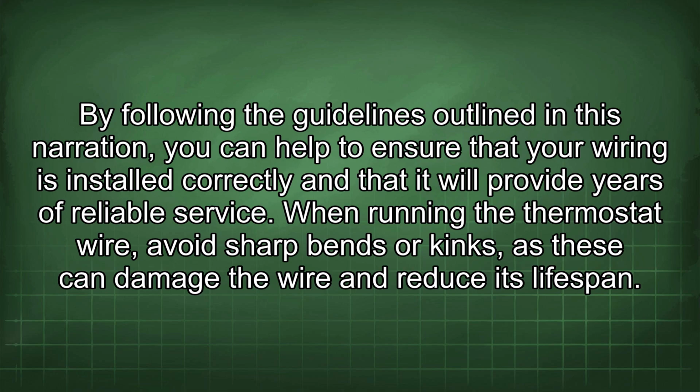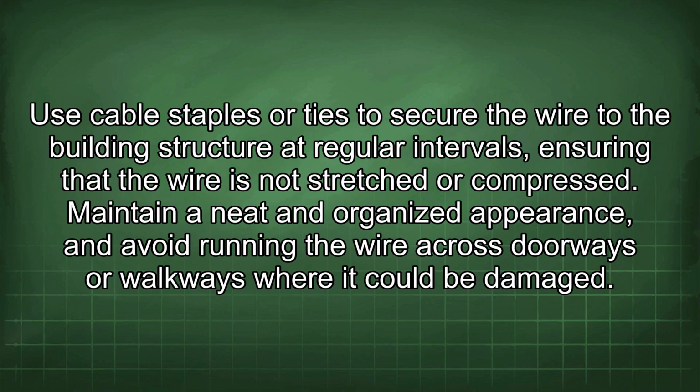When running the thermostat wire, avoid sharp bends or kinks, as these can damage the wire and reduce its lifespan. Use cable staples or ties to secure the wire to the building structure at regular intervals, ensuring that the wire is not stretched or compressed. Maintain a neat and organized appearance and avoid running the wire across doorways or walkways where it could be damaged.